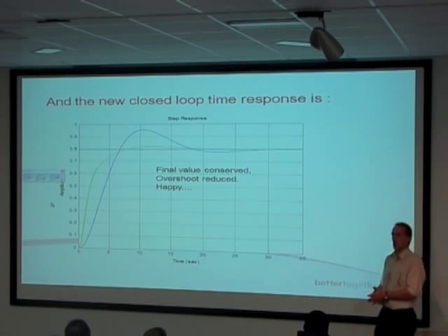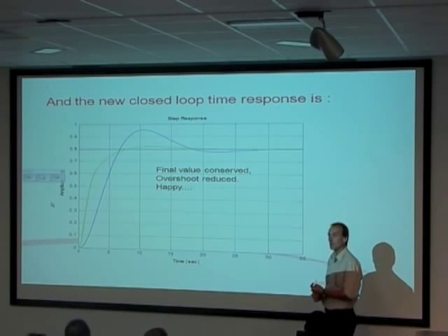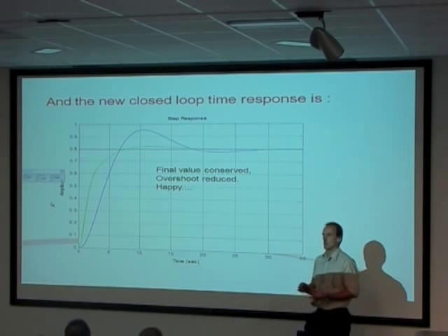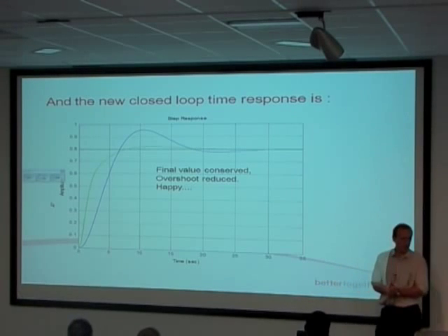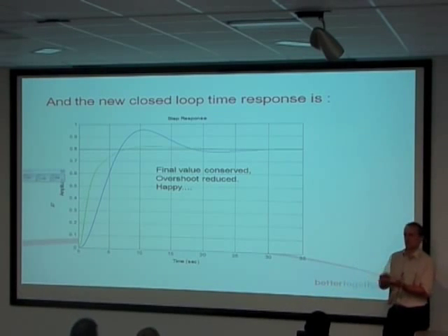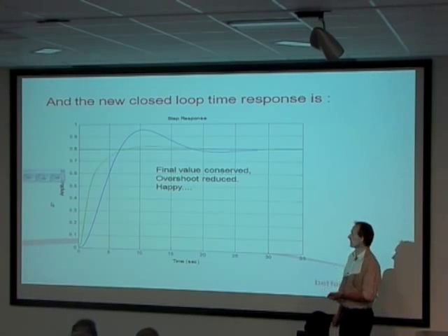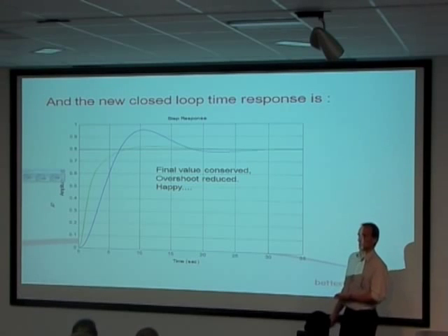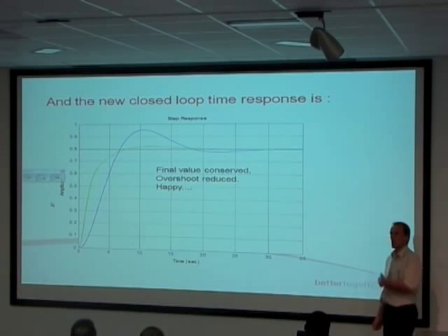So we've managed to introduce a compensator using a standard pattern. I picked a lead compensator for this exercise. If you wanted to design one, you go into the compensator design books and there are off-the-shelf formulae for how to do it. So that gives you the numbers to put into your lead compensator. Okay, so it's a very straightforward design process.